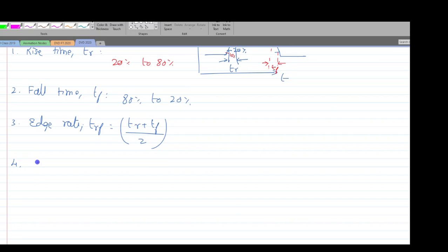Now I'll talk about what is known as the setup time and hold time. We know that these two timing parameters are not related to compound logic, but to what is known as sequential elements. When I say sequential elements, both these timing parameters are related to latch circuits as well as flip-flop circuits, or edge triggered circuits.